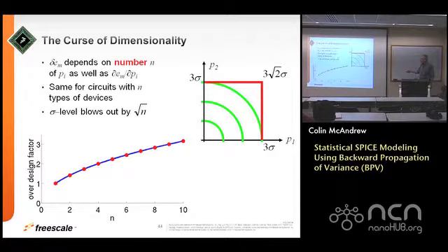that I'm varying, if I put plus 3 sigma in each of these, I end up at 3 times overestimating what the variation in my final thing should be, with the caveat again that without knowing the sensitivities, I don't really know what it is. That's only in the probability space. And note that this is not just for the number of parameters in the models. If I take TOX, VT, delta L, and do that, then I've got square root of 3 variation.